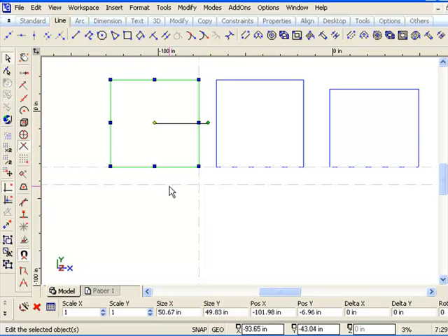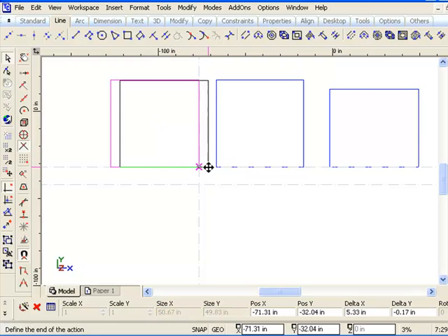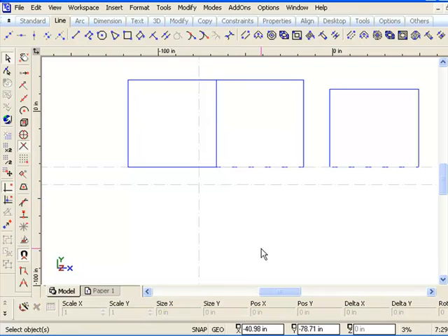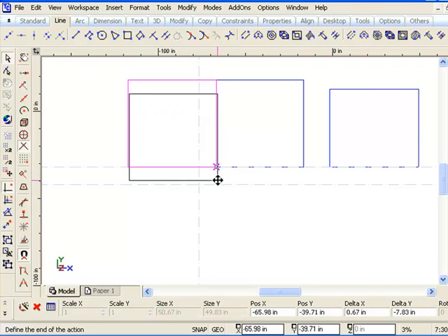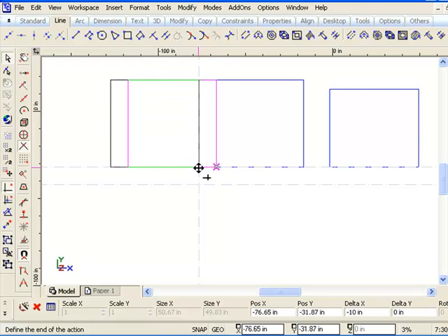If you edited the reference point type of thing, yes, that would be the old way of doing it. You would have the reference point. I'd press D and you'd go V over there, and you'd position the reference point over here. So you'd click there, and then you'd pick up the reference point, and then move over there and click over there, and it moves that object. But this whole new delta thing really does make a huge difference to position objects up and down, or move them, or change the object.